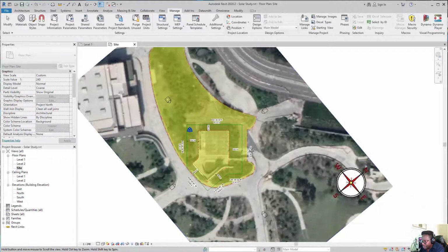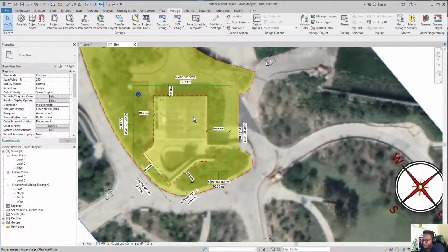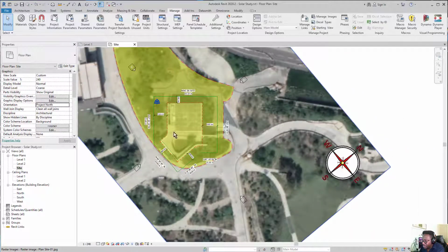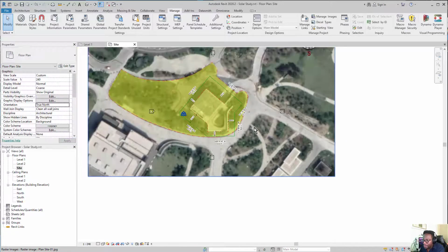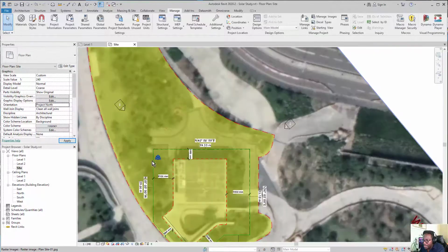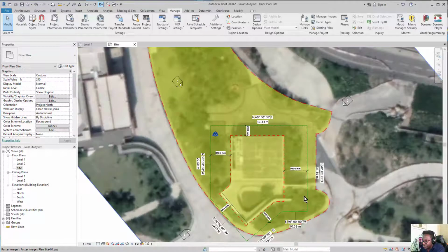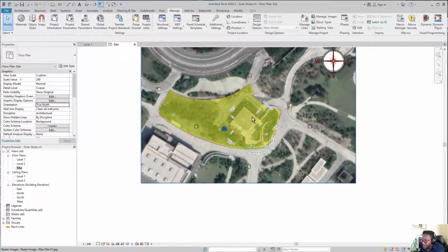Now notice what we'll have now are two types of north. We will have a project north, and then we'll also have a true north. Now when we're drawing lines, we can always switch to project north, and that will make our lines easier to draw because everything is in straight lines. All right. Now let's go back to true north. All right.